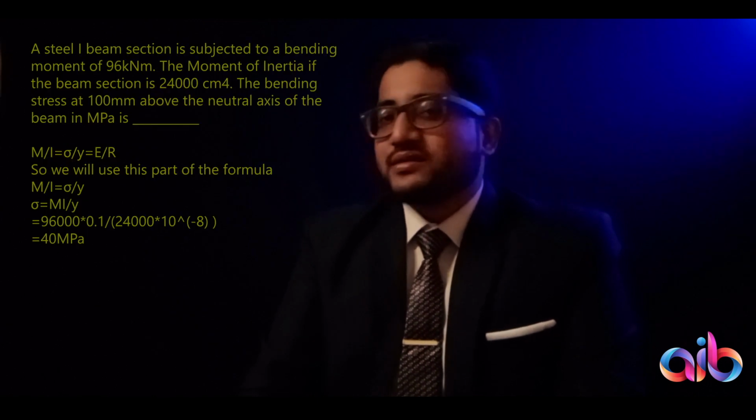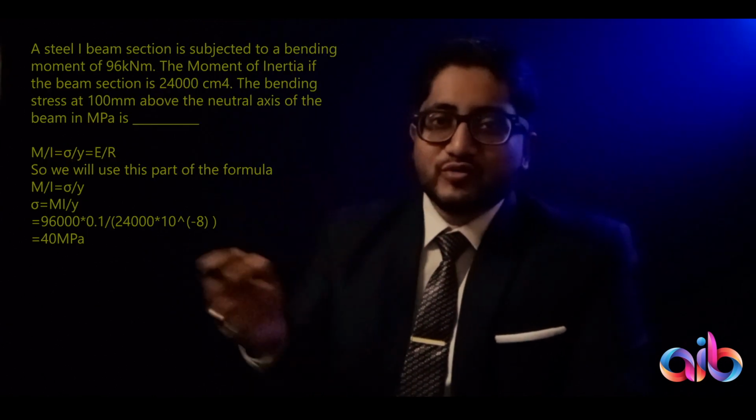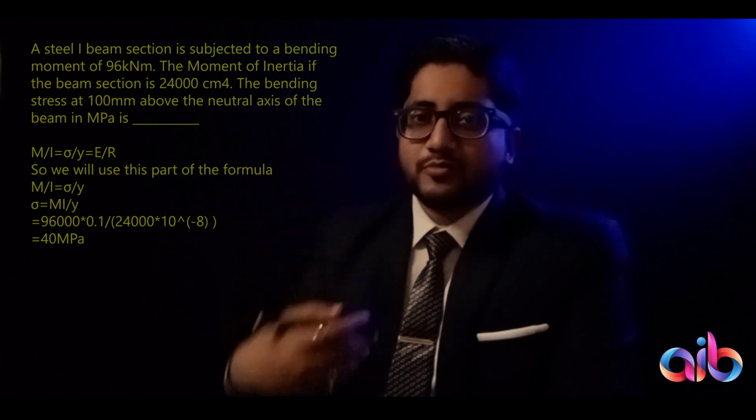Now this question I'm not going to solve mentally the way I'm solving the other questions, because a lot of calculation is involved, but the concept behind these kinds of questions is very simple. It's a question on bending of an object, or the bending theory. They've said there's a beam which is bending, and they've given you a moment of inertia, a moment or whatnot. What have they asked you to find? They've asked you to find the bending stress, which means they must have given you the moment of inertia, the bending moment, and the distance of the neutral axis from either the top edge or the bottom edge.